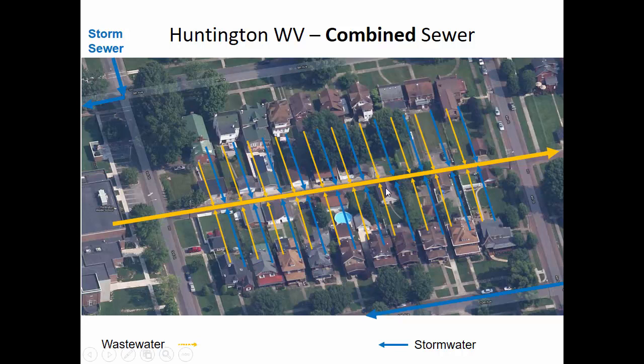we have a combined sewer, there's a base flow of the wastewater, people flushing the toilets, running the shower, washing their dishes. That's going to be some of the water that's in these pipes. And then we're adding an additional load on top of that of the stormwater. And today I'm going to teach you the simplest way of understanding how much flow is wanting to get into the pipes. It's a simple model called the rational method that can allow you to analyze the network.